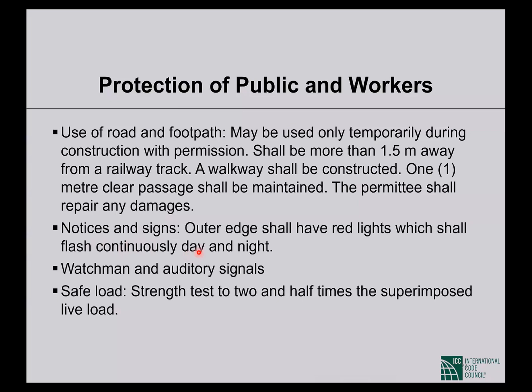If we use some place which is near to public use, then we should have flashing red lights. You might have seen some of them with the metro rail construction or elevated expressway construction. There you can see places where red lights flash. That is actually a code requirement.